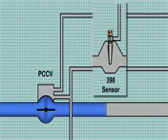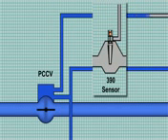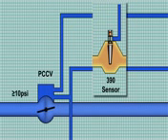When the engine starts, the PCCV is open. As the pressure rises above 10 psi, the PCCV starts to close. As engine speed increases, so does the bleed air temperature. When bleed air temperature reaches 390 degrees Fahrenheit, the 390 sensor begins to open, reducing control air pressure. This causes the PCCV to open.